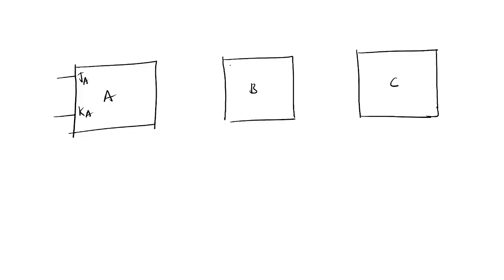So how many flip flops are required? Three flip flops are required. I'm using flip flop A, flip flop B, flip flop C. I'm using JK flip flop. So JK flip flop means this is JA KA, JB KB, and JC KC. For QC, we can use either a T or JK flip flop, your wish.